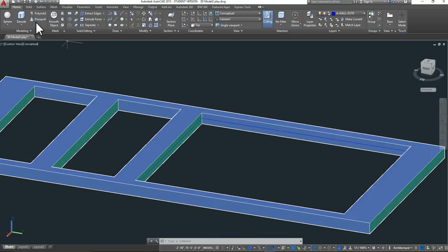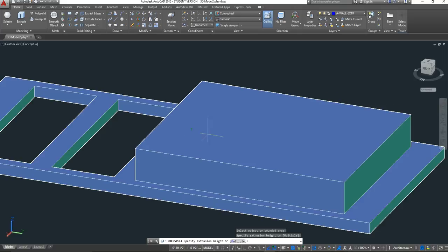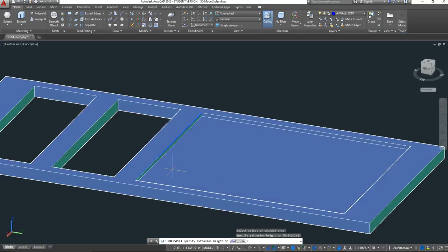And so now I just want to get my press pull tool again. Again, I'm in my home tab, press pull. And I want to hover until I see that full polyline highlighted. So right there, you guys see it's highlighted. I'm just going to click once. And then I'm just going to bring it down just slightly because it'll come all the way up there, and just click. And it doesn't really matter how much you bring that out. You just want to click once. If it comes all the way up here for you, you just want to click it so that you have a little bit of depth, a little bit of panel in that door. So it doesn't have to be perfect, just as long as you get it in there.